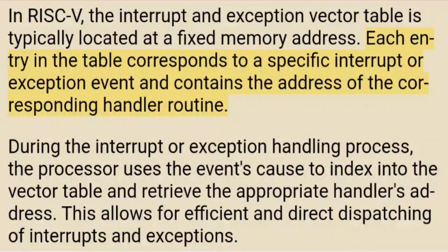Each entry in the table corresponds to a specific interrupt or exception event and contains the address of the corresponding handler routine. During the interrupt or exception handling process, the processor uses the event's cause to index into the vector table and retrieve the appropriate handler's address. This allows for efficient and direct dispatching of interrupts and exceptions.